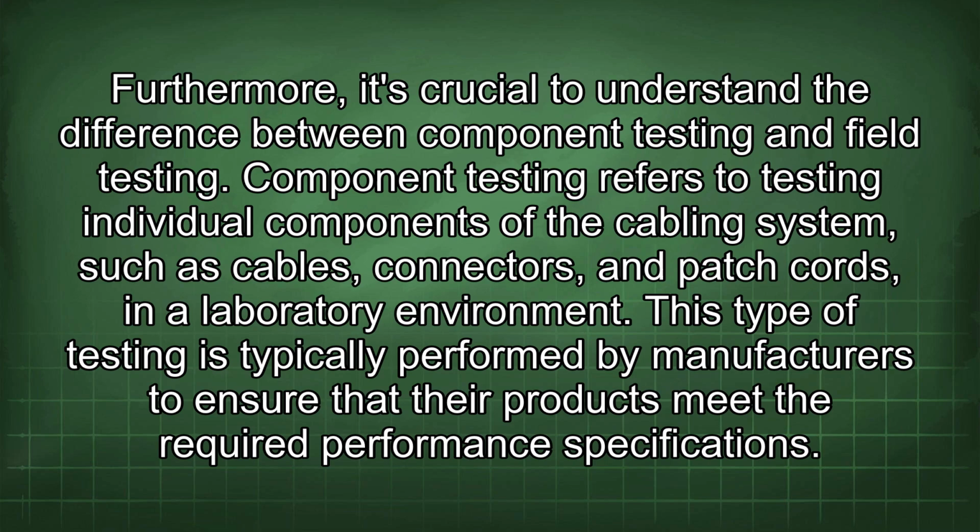Furthermore, it's crucial to understand the difference between component testing and field testing. Component testing refers to testing individual components of the cabling system, such as cables, connectors, and patch cords, in a laboratory environment. This type of testing is typically performed by manufacturers to ensure that their products meet the required performance specifications.